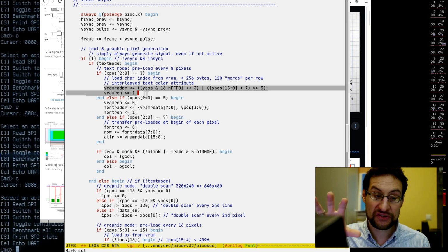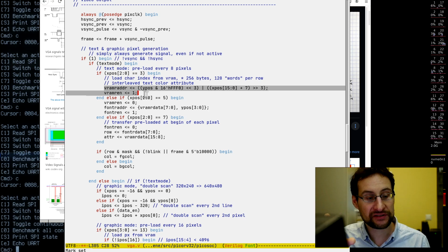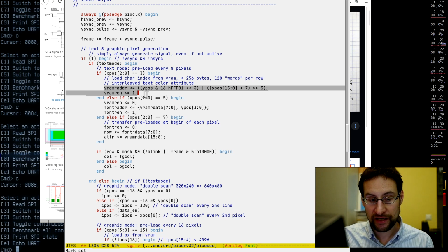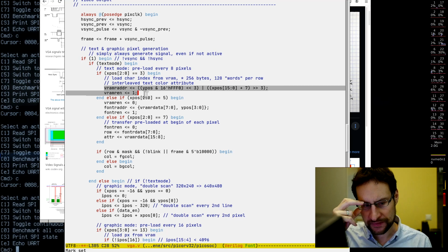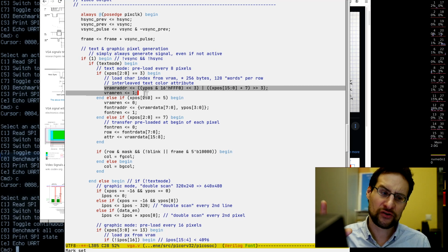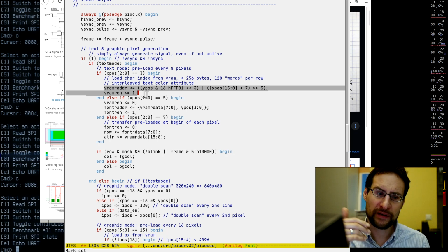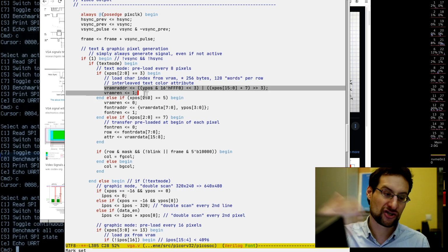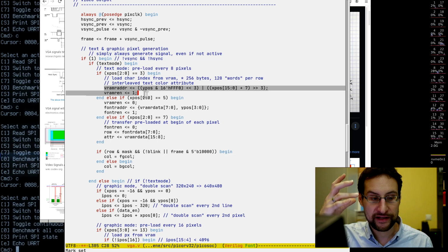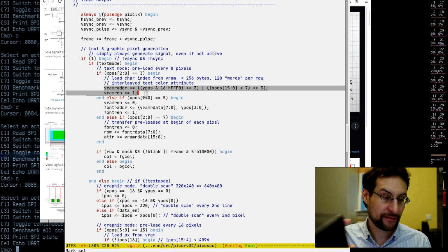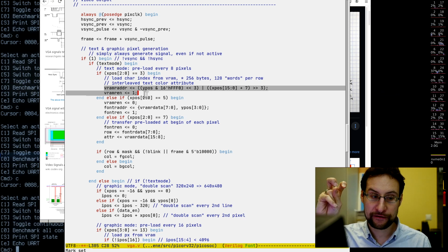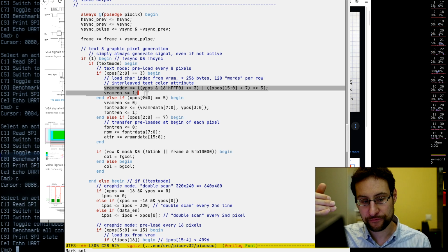The Yosys timing will not check this for us. Yosys timing will tell us this design is good for 14 megahertz in this iCE40, although we run with 26, so we need to be a little careful. This is also the point of many other examples. They usually synthesize at 12, 13, 14 megahertz, although they run much higher, even as high as 1920 by 1080, without validating the clock frequency for the pixel clock. It's like, yeah, we are lucky and maybe it works.